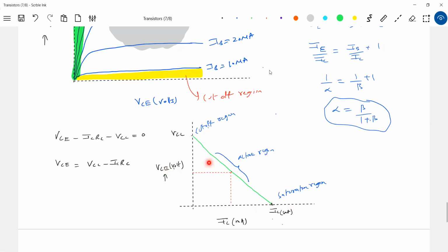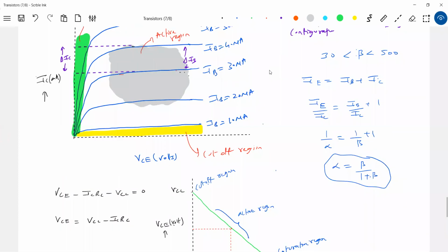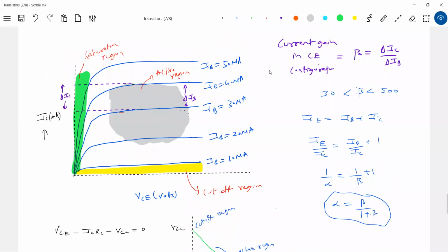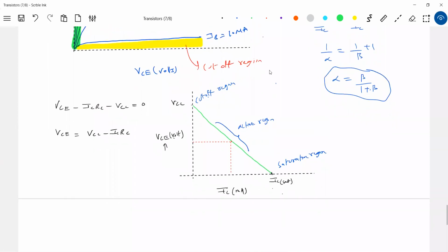In the books, if you see the integrated book, they have discussed this one. It is very useful when you plot the VCE versus IC graph. The other graph is a little different. This is IC versus VCE for different values of IB. Why do we use this graph? To calculate the beta of a transistor and to get the output resistance. For that purpose, when we are using a transistor, I prefer this one.